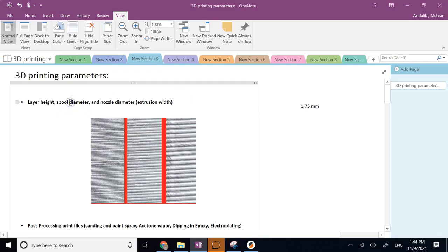But the plastic that comes out of the hot end does not have the same diameter. Typically, it goes from 1.75 to something close to 0.4 mm. Now, again, is that the only diameter of the extruded plastic? No. But this is kind of the most common nozzle that there is. I have seen nozzles from 0.1 mm to 0.8 and more.